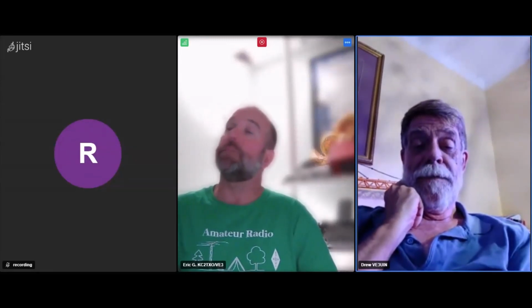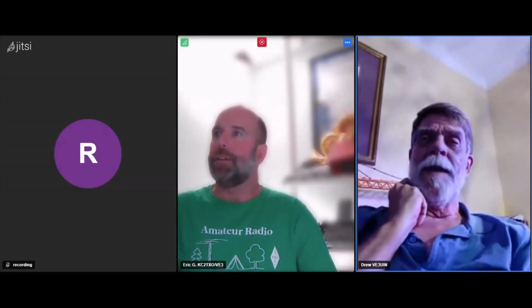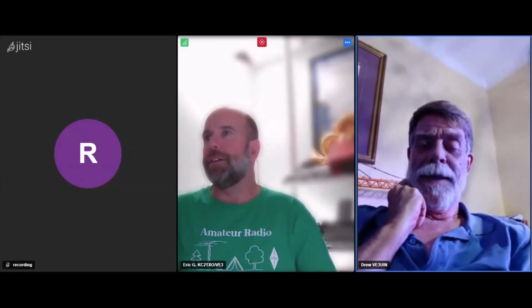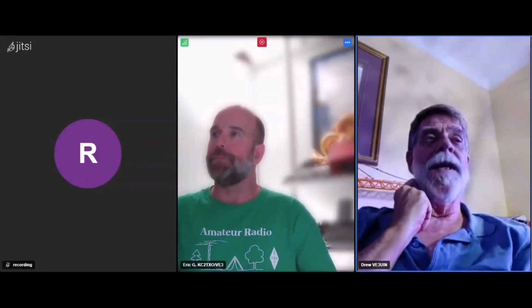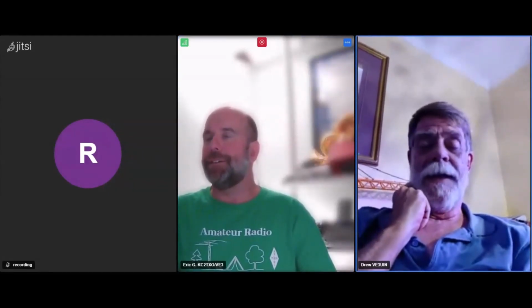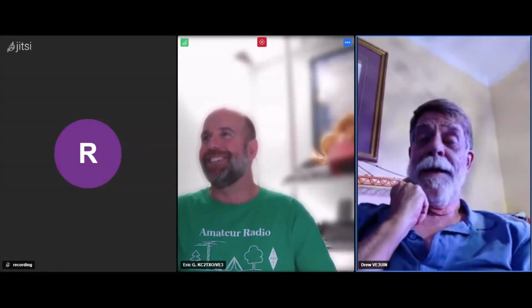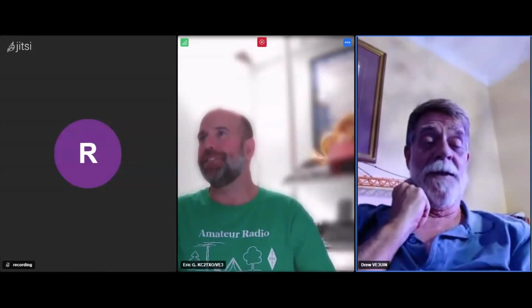And I know the QCX, that's the one Howard was talking about. If you build it for 9 volts and feed it 12, it's done. Yeah, blows up. So these QRP kit rigs are a lot fussier than your standard commercial. You know, this old ICOM I got, I'm pretty sure it's been kicked down the stairs 20 or 30 times before I bought it, because it's looking pretty ragged, but it doesn't care. It just sits there and keeps working.